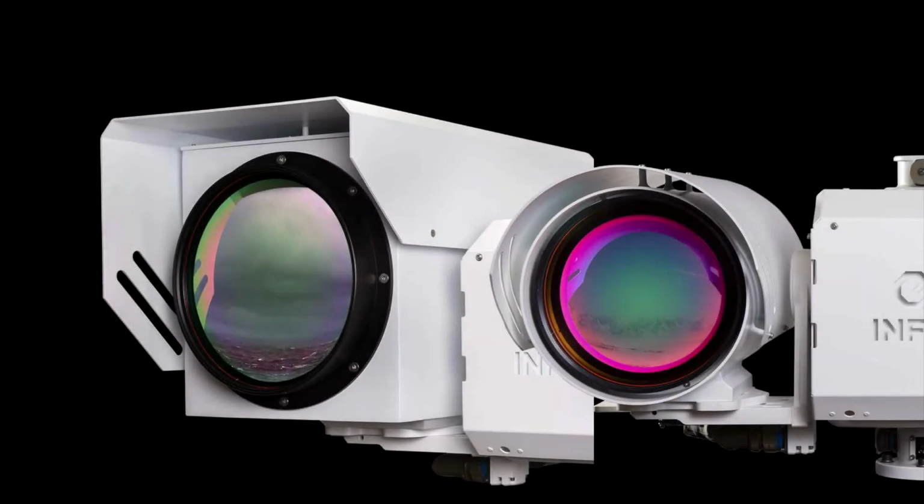Now, it is important to know that the thermal sensors use lenses like the visible cameras. Just in this case, the glass material for those lenses is chosen to be transmissive to the LWIR range of wavelengths. Typical materials for this are germanium, silicon, zinc sulfide, or chalcogenide. Apart from these differences from the visible optics, the rules of refraction and focusing are the same.